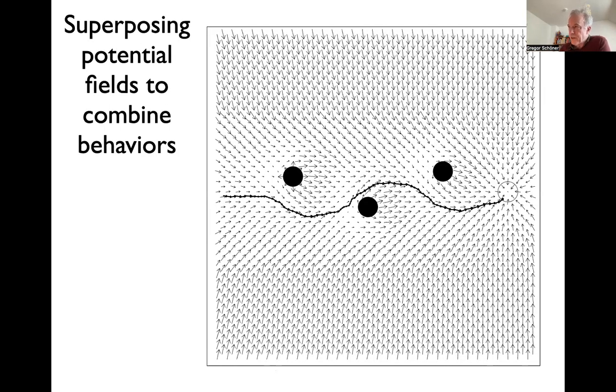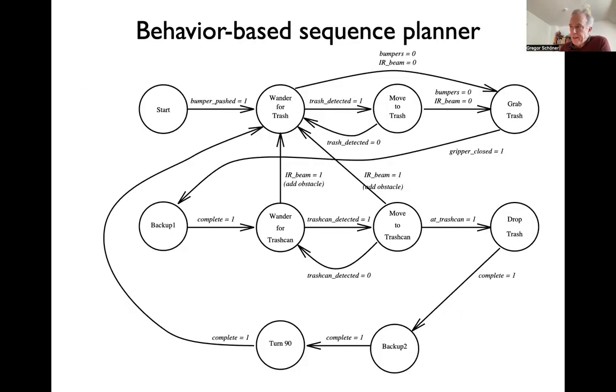So this is an example, moving along a path that works under some conditions. And they often have some form of planner. So it's not a real planner, it's a reactive planner, sometimes formulated as a finite state machine, where they will activate or deactivate some of these elementary behaviors, which they call schemata, in response to certain sensory conditions that they detect. For instance, if you detect that some of your bumpers did something, then you have to, I don't know, do something else. I just took that from one of their papers without tracking exactly what they do. So the design is designing this kind of thing.